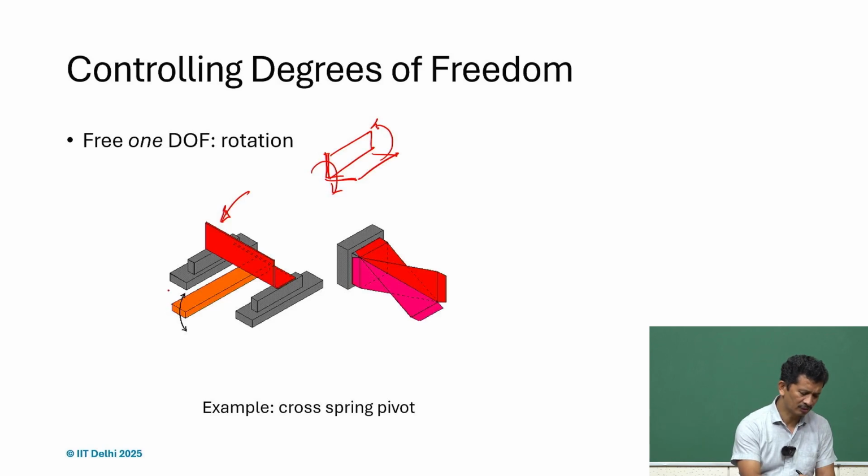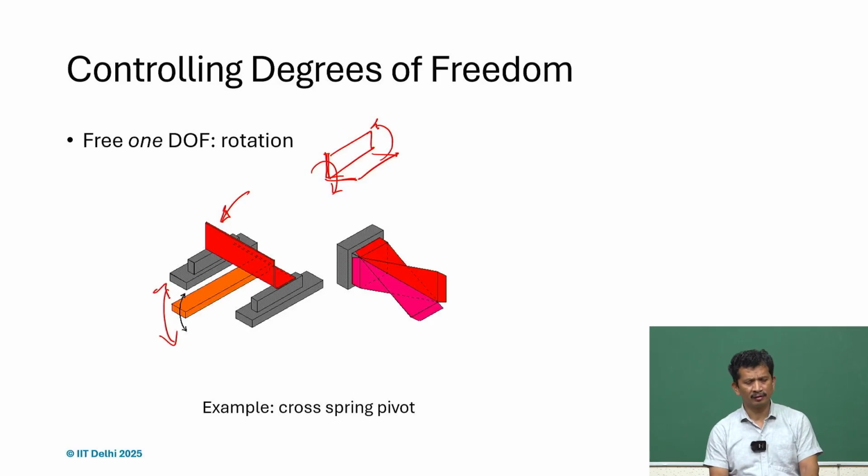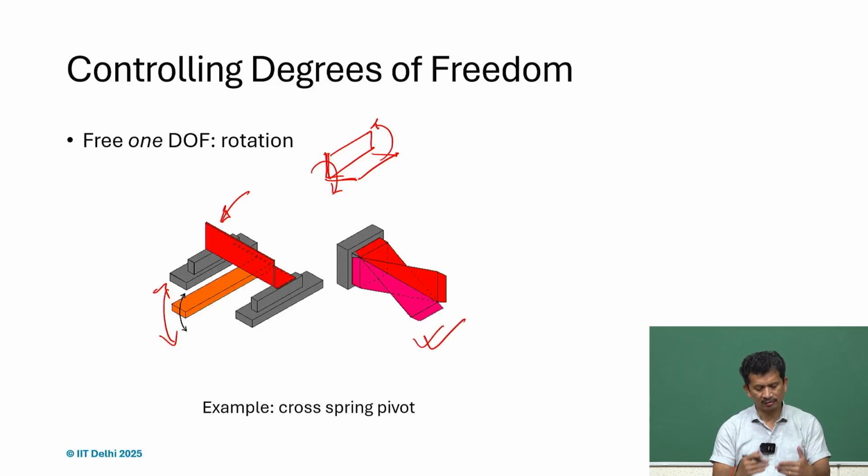And that is what we see here. So, if we just weld an orange part to that L section, we can easily twist. There is another embodiment here, and here there are two, very difficult to visualize, but it is along the seam, and basically it is a symmetric design, and we have 2 L sections welded together to get these kind of pivots. So, it will also provide rotational degree of freedom. All other DOFs are constrained except the rotational degree of freedom along the axis.